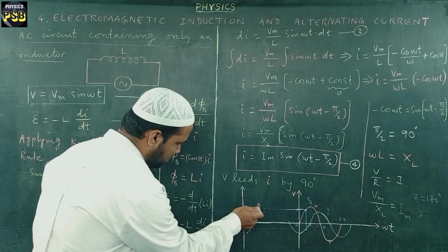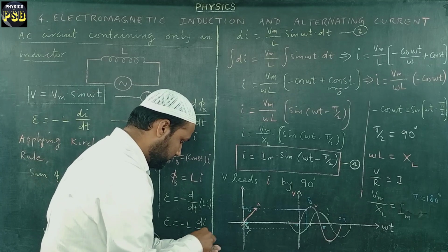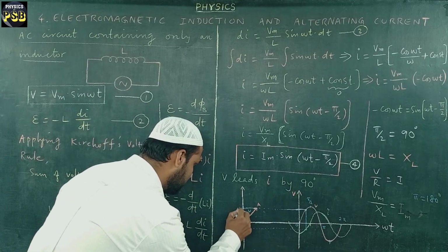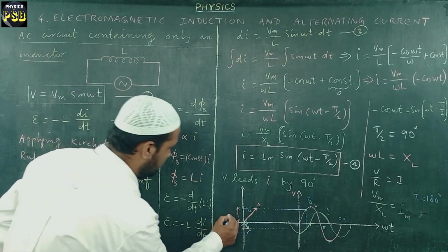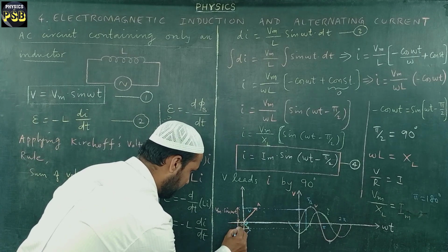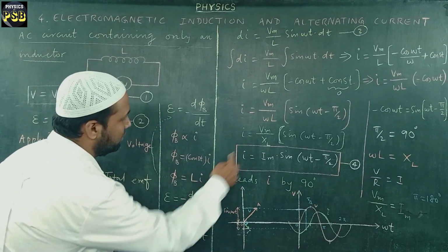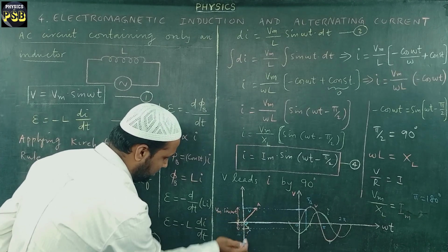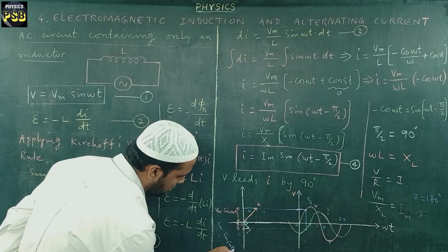Now, from this point, if you draw the projection, it falls on this. The same I do here as well. It's a projection of this phasor on the y-axis. This projection will provide us the instantaneous value of alternating voltage. This is the value of V. This is nothing but Vm sine omega t, and this height from here to here, which is obtained from the projection, provides us the value of instantaneous voltage. That is Im, right here. The space is not sufficient, so I write it this way: Im sine of omega t minus pi by 2.